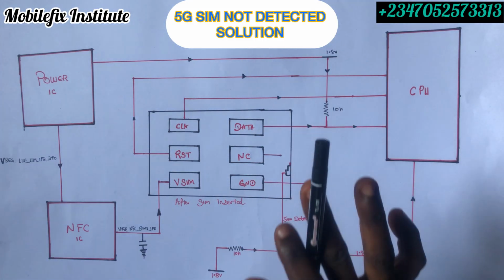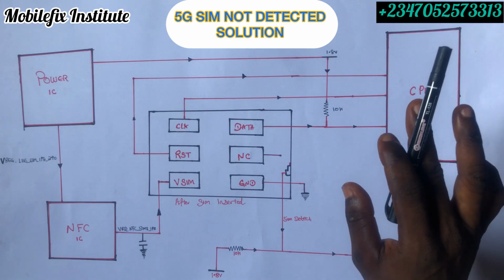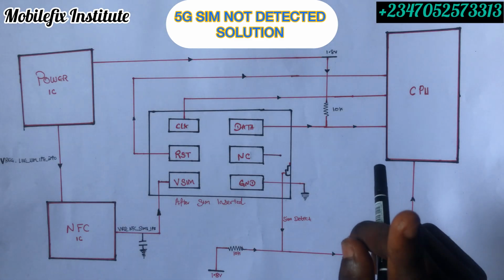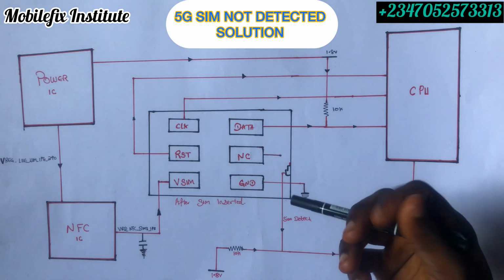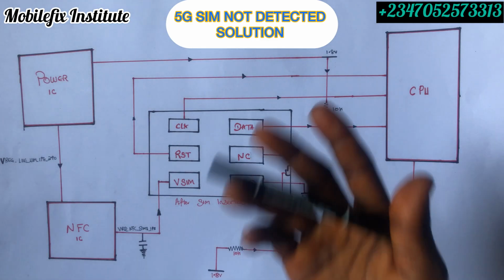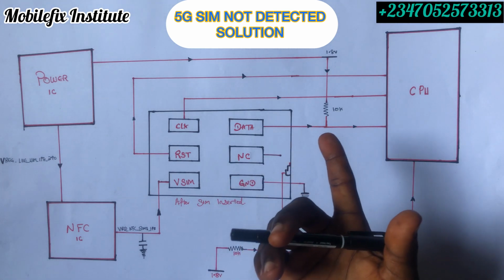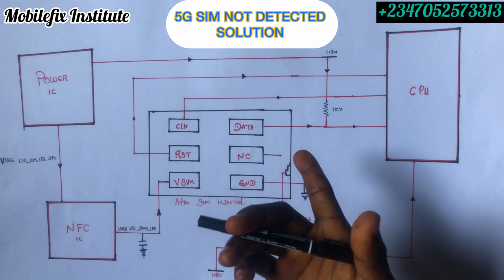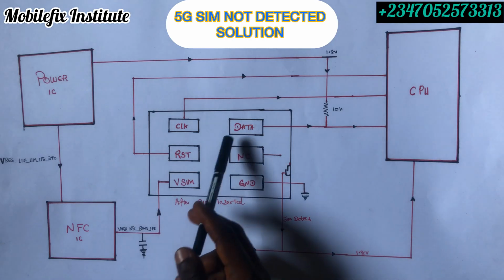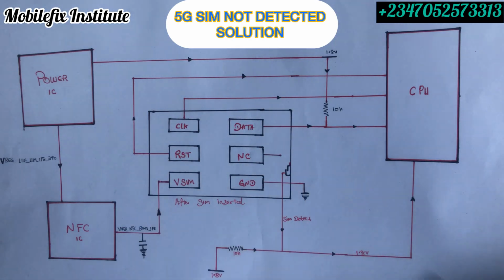When your phone shows SIM card not detected, the first thing that has to come into your mind is that you have to change the SIM. Sometimes you might put a faulty SIM, or the SIM is not good, then your CPU will not detect it. So you have to test another SIM. After testing another SIM and you see that it still does not display the SIM card, the next thing you have to do is to open the phone and examine this SIM tray port. This is our SIM tray port, also you can call it SIM jack.